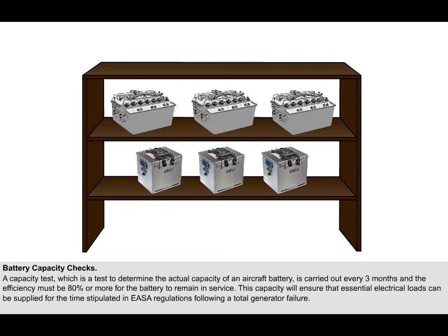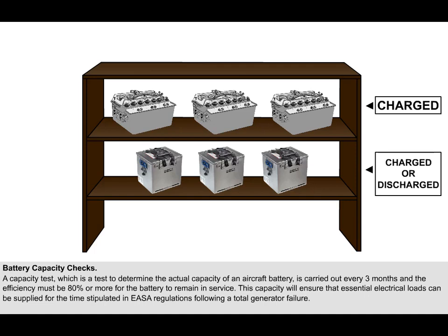Spare batteries will be held ready for use in the electrical workshop. Lead-acid batteries are stored in a charge state to prevent deterioration of their plates. NiCad batteries can be stored in a discharge state with no detrimental effect to the battery, and therefore have a longer storage life or shelf life.